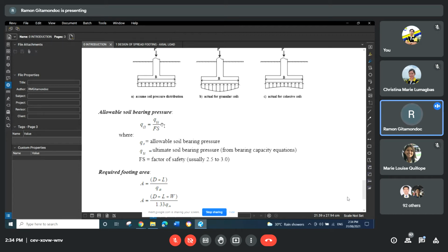If the data is uncertain, then you have to provide a larger factor of safety. Or if the resulting data is too variable, then you induce a larger factor of safety into the design, because no two boreholes will yield exactly the same result. They might give you some similarity, but in some cases, they are also too different.